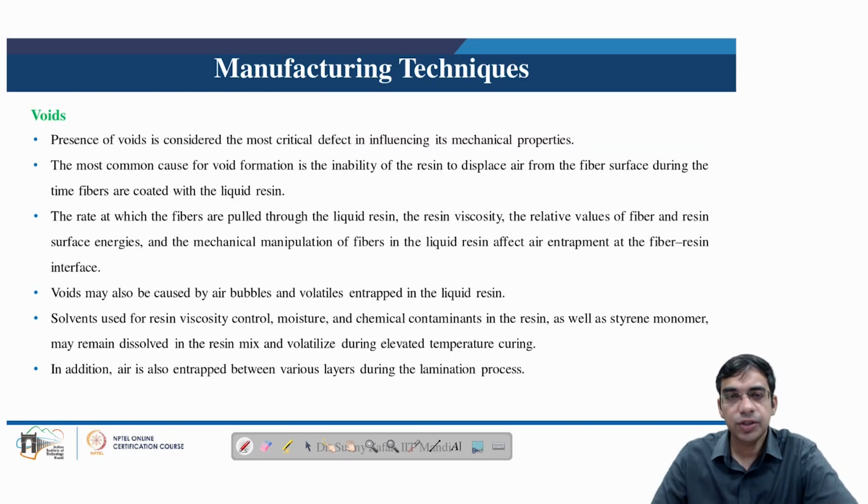Next is the estimation of voids. Voids are fundamentally very difficult to completely eliminate in any manufactured composite part, but efforts are always put in to minimize the void volume fraction as low as possible. The presence of voids is often considered the most critical defect influencing the mechanical properties of the composite part, because it is the presence of voids that makes a discontinuous interface between the fiber and the